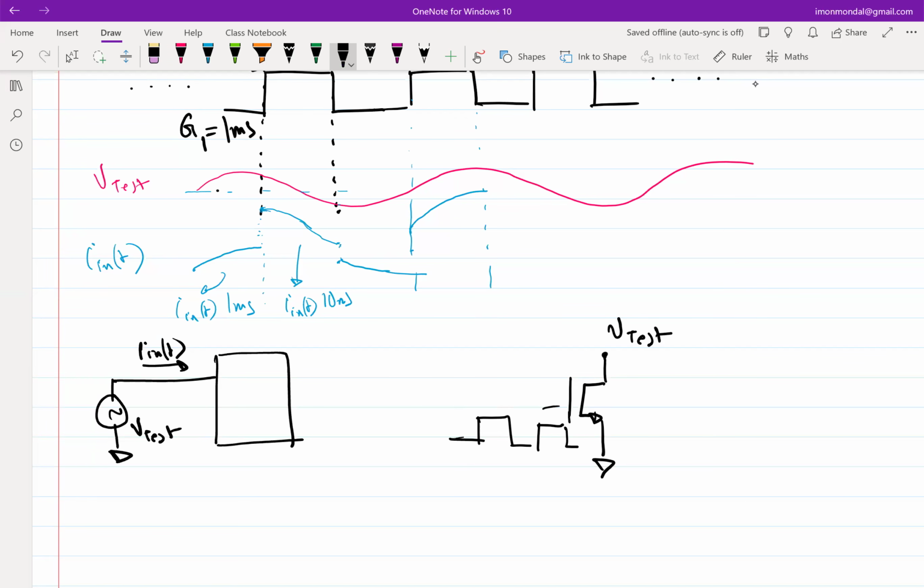So the lower part, what do you want it to be? I'm asking for this voltage. VDD by 2 to VDD. Okay. And why do you say VDD by 2? What was the thought process behind that? It will still be above threshold to allow some current. Okay, good. So do you agree that this kind of works, right?